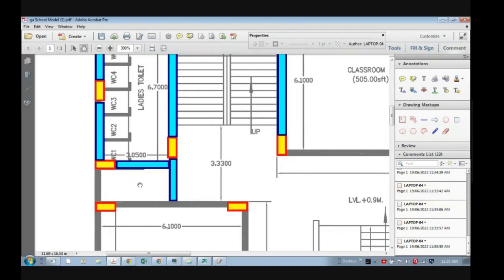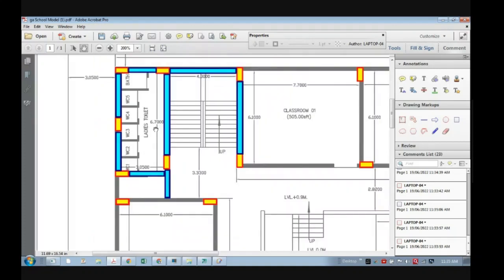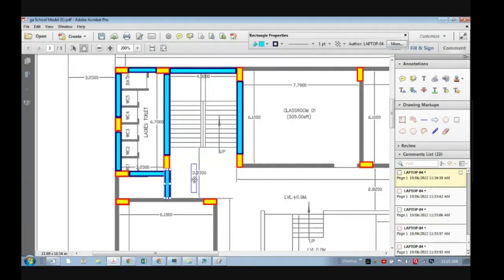Okay, ये समझ में आया? Now और बताओ कहाँ कहाँ चाहिए? So beam decision we are taking below the walls is first case. Then we are taking, अभी यहाँ wall थी क्या? Is there wall over here? नहीं है passage में. Yes or no? Yes sir. So why I am taking the beam here then? वो क्योंकि हमको जो दूसरी बीम उधर से आ रही है उसको सपोर्ट करना. Because I want to raise this beam on this beam, and that's why I'm taking that beam.